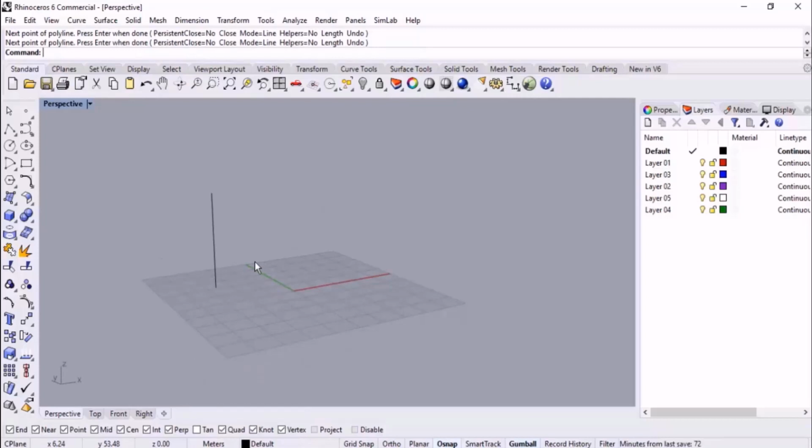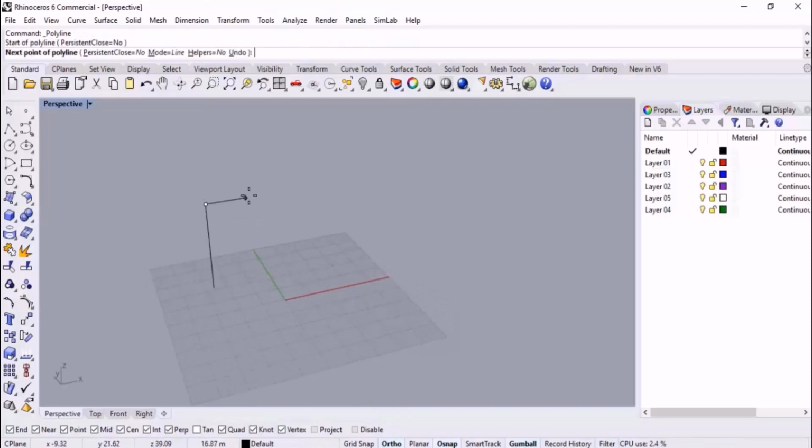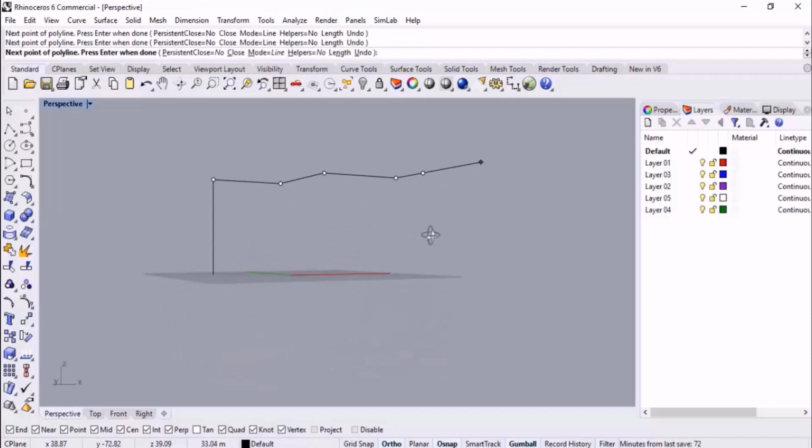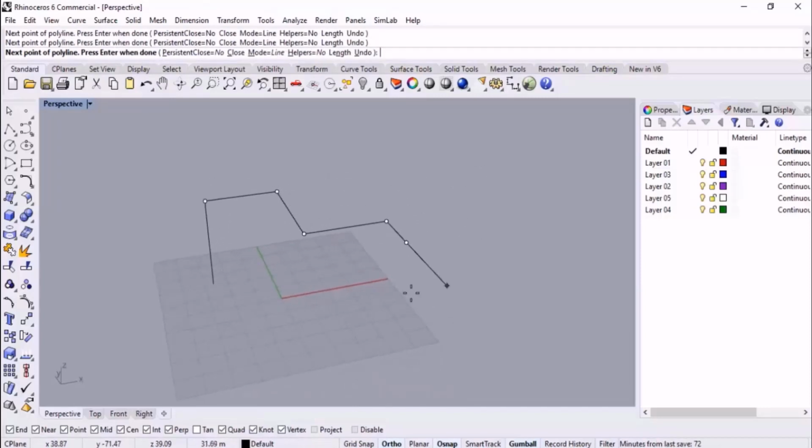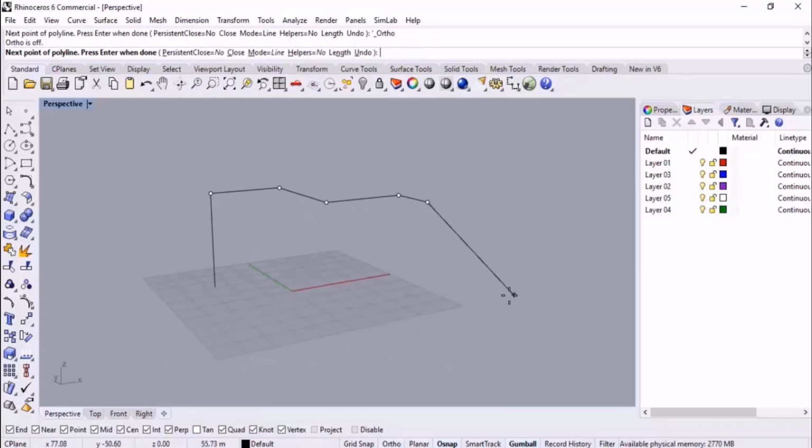As I told you, some of the auxiliary commands constrain the drawings to the same plane, just like ortho. Here if I enable ortho, as you can see, the movement is restricted to points at the multiple of the specified angle from the last point created, so changes in the plane are impossible. So we got them at the same height or level.